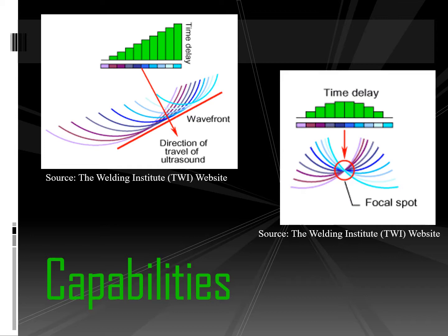Phased array transducers differ from conventional ultrasonic ones by having multiple crystal elements, which are all individually wired. This allows excitation of each element to occur independently, or in phase, which produces some unique capabilities. Timing of excitations can be programmed so that this sound energy interacts to converge or focus at a predetermined depth. Delayed firing order can be utilized for beam steering and focusing to optimize inspections.